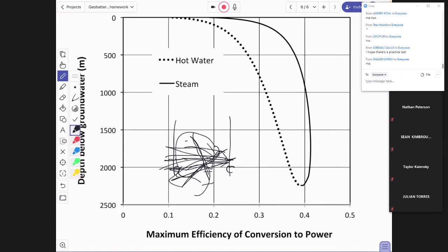Now, again, you'll learn something about this as we start talking about entropy production. But it ends up that this works really well, in part because I'm transferring a huge amount of energy with relatively small temperature differences, right? That steam comes in, it sees temperature differences, maybe a couple, 4 degrees C. That's all it takes for getting the storage that we need. So the temperature differences coming in and out are really small. That gives us really a high exergy exchange. That's why it's working so well.